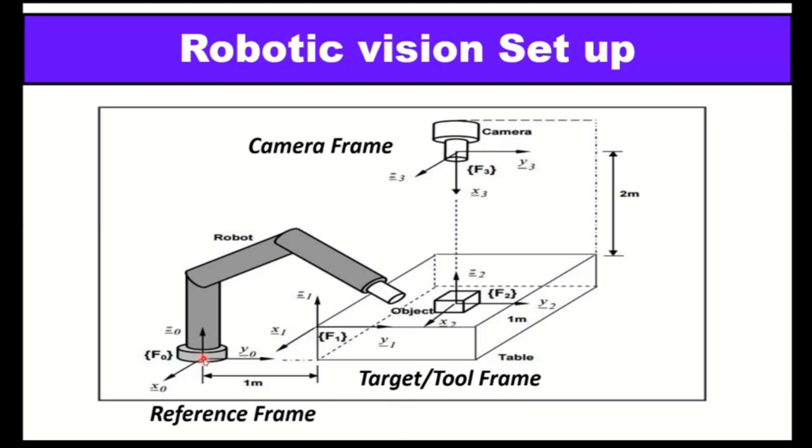This is what we call the reference frame, wherein the base is generally fixed and then each of these joints operates, that is moves, and each movement creates a coordinate, and all this measurement or control of the movement is with reference to the basic frame called the reference frame.